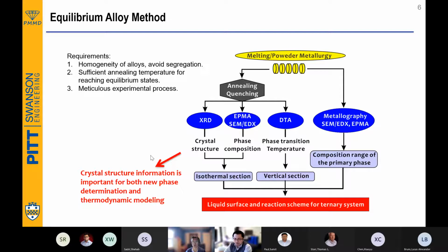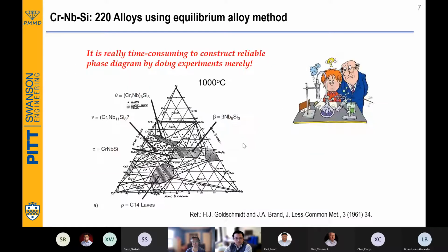A lot of people have probably heard about Scheil simulation. This is a kind of confirmation of Scheil simulation, sometimes at a basic fundamental level of research. The idea is, if you know an alloy, usually a conventional alloy has at least 5 or 6 components. You would like to say, at what temperature will this have different phases, and what are these phase compositions? What are the properties of these phases? Do you need to introduce enough strengthening phase to make sure the mechanical performance is right?